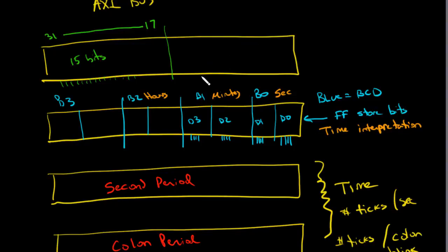Finally, what I can do is I can pay attention to the idea that I need to be able to pick one of these modes. And so mode 0, for instance, might be the bitmap. Mode 1 would correspond to the BCD display, and then mode 2 could correspond to my time display, and mode 3 could be future use.